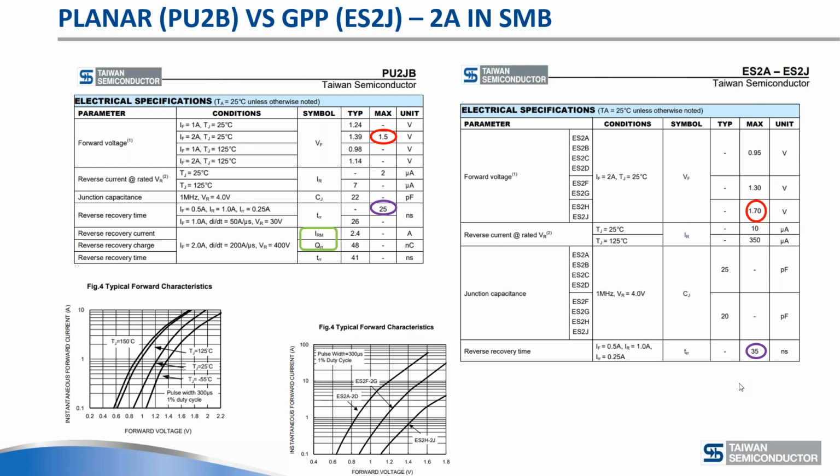The one thing I didn't circle here, but would like to point out, is that the leakage current here is 2 microamps, which is better than 10 microamps. Not so much difference, you would say. But the advantage becomes clearly outspoken at the high temperature of 125 degrees C. You see the 7 microamp here versus the 350 microamp maximum spec here. So that's a clear advantage.